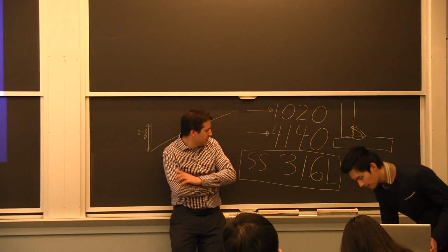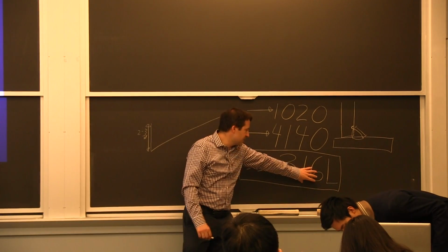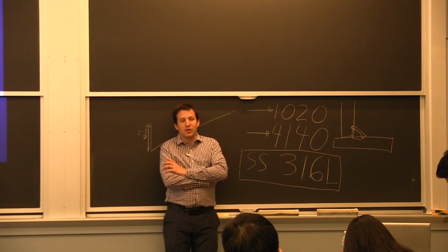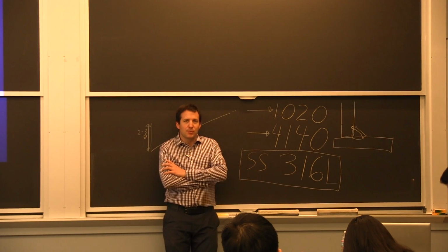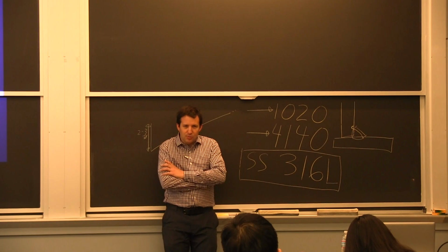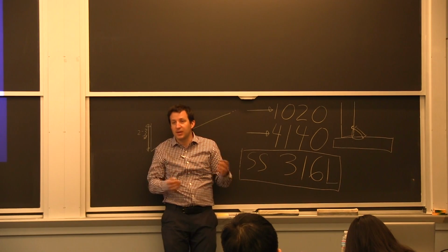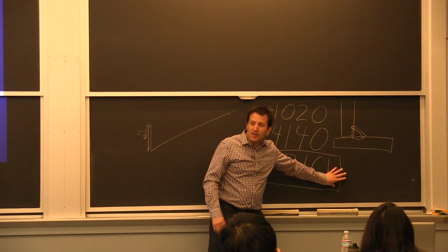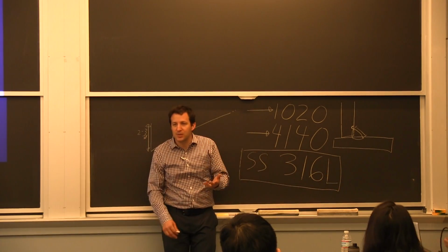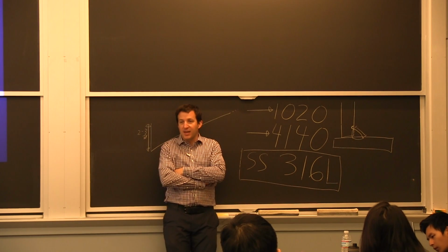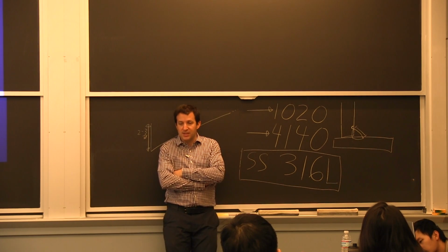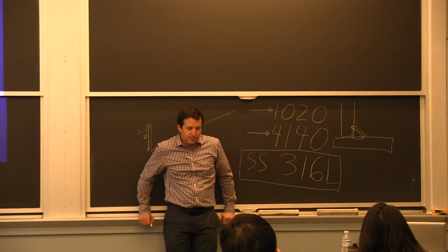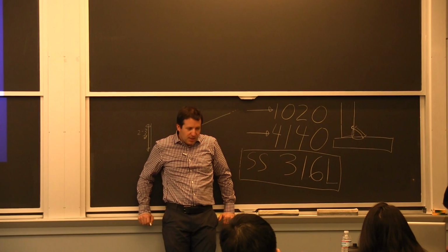Most stainless steel now, even if I was to buy a 316, will probably come as a 316L, because it's not too much more work to produce the low carbon. It avoids them having to carry both. There are no real advantages to not having the L. So even if you buy a 316, it could be a 316L. Is it guaranteed to be a 316 low carbon? No. So you still want to put it on, but it's only the chemical part.